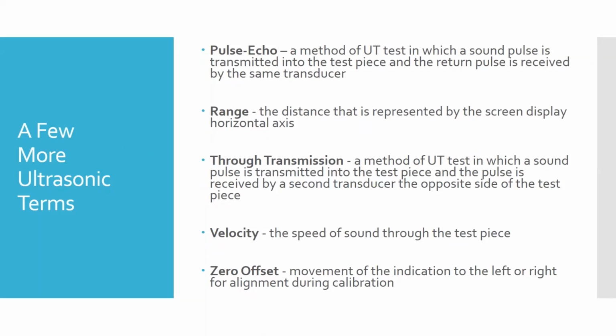But what we have to do is we say, okay, this probe, if we couldn't offset the zero, the signal we would get would say, well, zero is down here, down at the base of this thing. We've got to offset it, move it to say, actually, the zero is up here at the very end of this delay block.